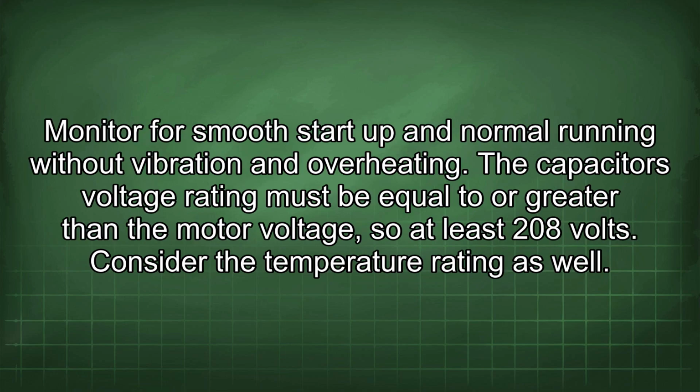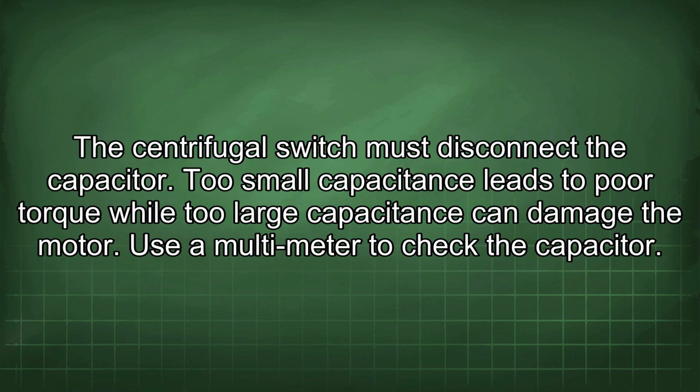Monitor for smooth startup and normal running without vibration and overheating. The capacitor's voltage rating must be equal to or greater than the motor voltage, so at least 208 volts. Consider the temperature rating as well. The centrifugal switch must disconnect the capacitor. Too small capacitance leads to poor torque, while too large capacitance can damage the motor.